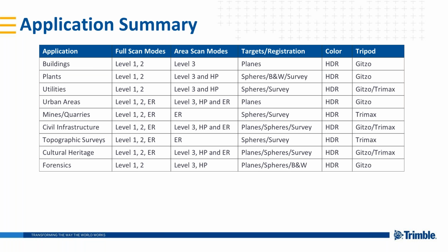The TX6 can be used for the other applications listed, but only for smaller scale projects. For larger projects with a faster scan speed, 340 meter extended range, or high precision can be of benefit to you, then the TX8 extended instrument would be the model of choice.